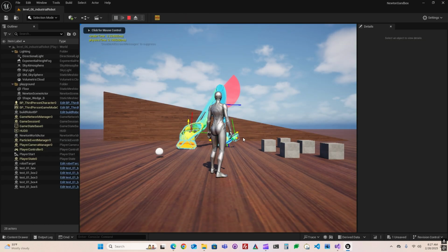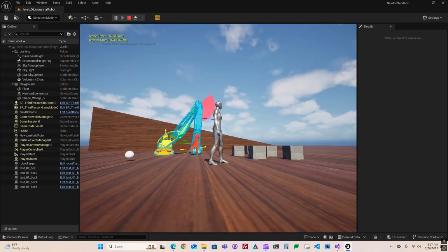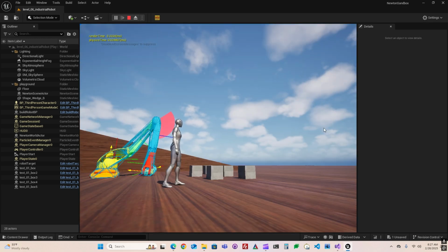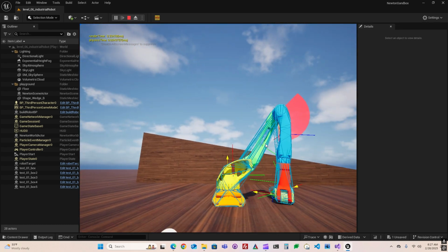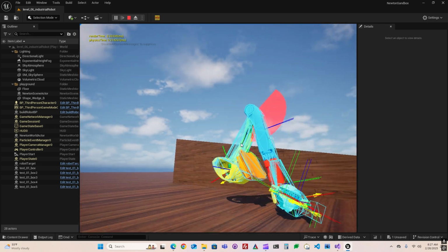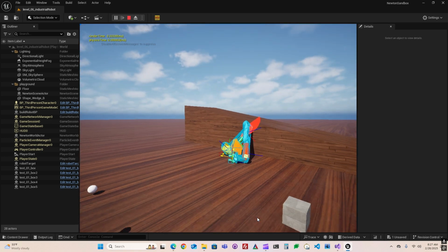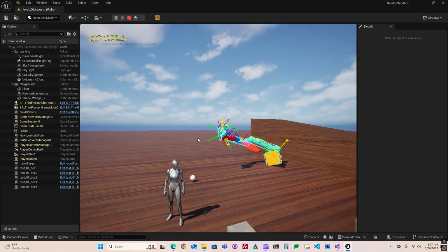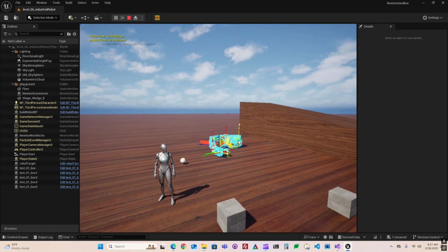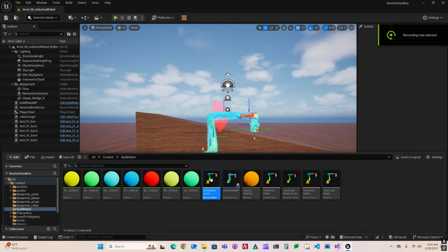The robot now moves with constraints, but still behaves like a ragdoll because the hinges lack motor functionality. There are two ways to motorize the hinges. Forward dynamics: each joint acts as a motor, trying to reach a target angle while affecting its child joints. This works well for predefined animations. Closed kinematic loop, inverse dynamics: it calculates the torque for each joint based on the desired tip position. It uses rigid body dynamics instead of traditional inverse kinematics, and is more suitable for robotics and other mechanical simulations. In this demo, we'll use the inverse dynamics method.